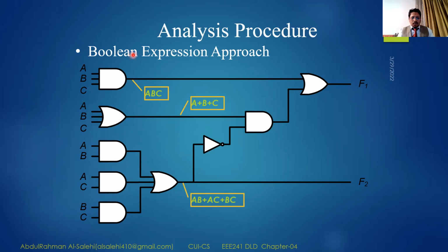And here, what we got from these results is that we just finished the first 2 levels of the transfer of the bits from the inputs to the outputs. So now, if I take F2, it is very clear that F2 is AB plus AC plus BC, because it will just come on this line to here.